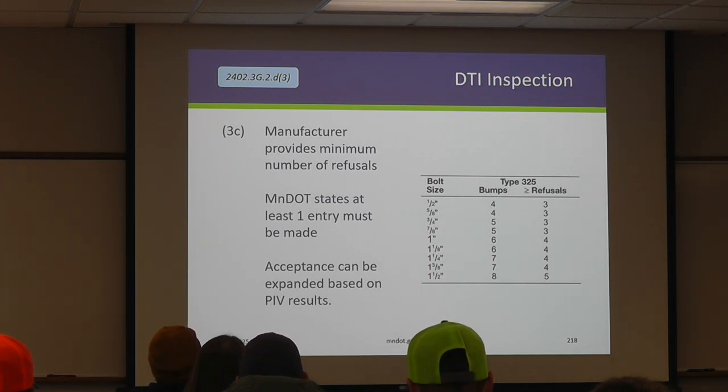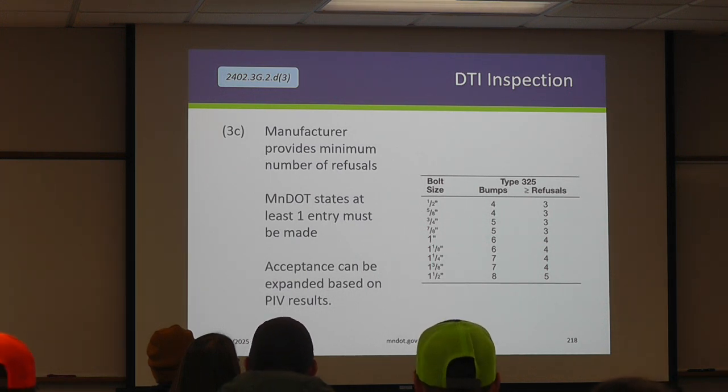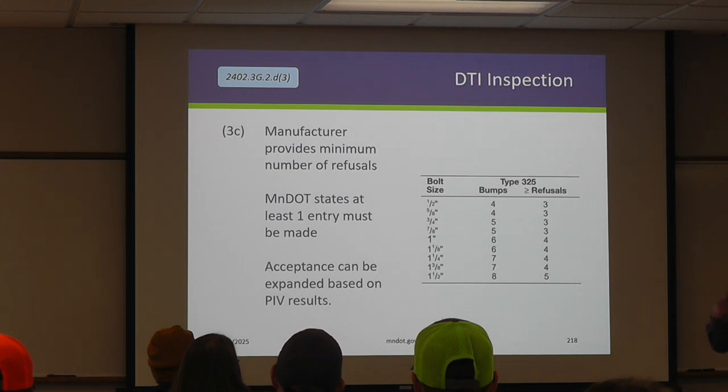This allows you to be out of the basket. Now, contractors will often struggle to maintain this because the DTIs are designed to crush at that point. And as you can see, if you're not the one operating the gun and looking at the DTI at the same time, it's hard to see this happen, right? I've been on a project once where the contractor said, hey, we're doing everything right, and these DTIs are all crushed. I said, all right, demonstrate it to me. So we go up, they snug an individual bolt, we check it.